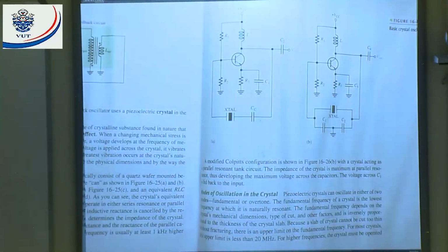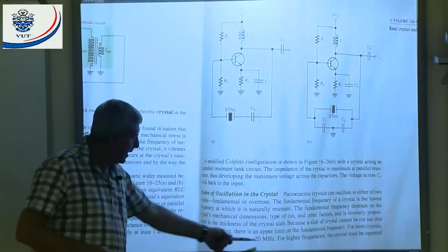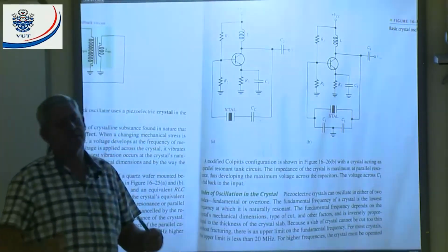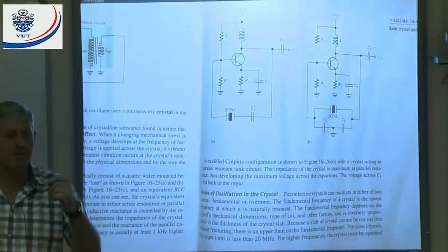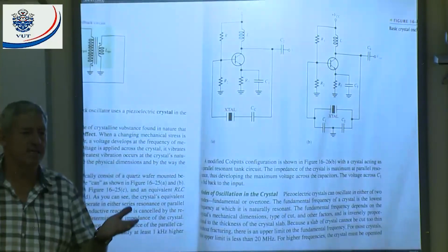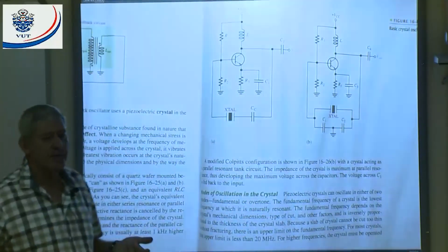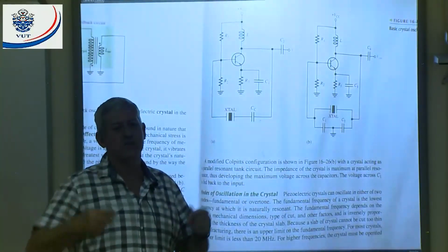All right, there are the two crystal controlled oscillators. Then we're going to talk about modes of oscillation of a crystal. Now, around about the upper limit of what they can get out of a crystal, the way they cut the crystal, is around 20 megahertz. We can't go higher than 20 megahertz because they can't cut it too thin, or it's going to splinter and break, all right? They can cut them fairly thin. But to go to higher frequencies, we're going to look at the fundamentals. Fundamental frequencies, then you can go to much higher values.